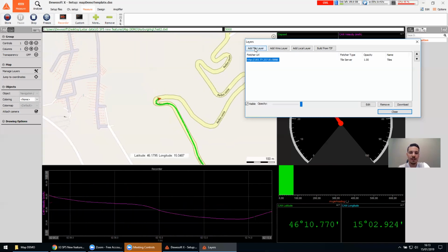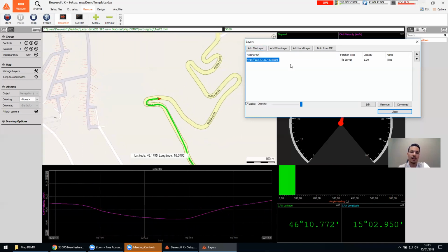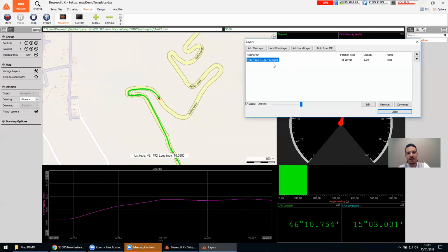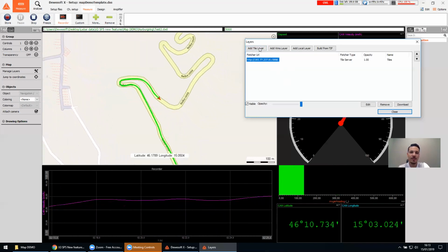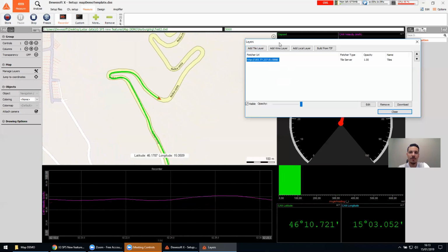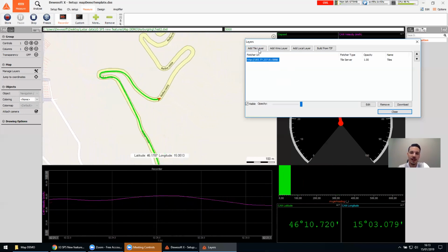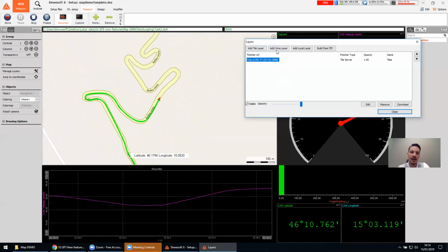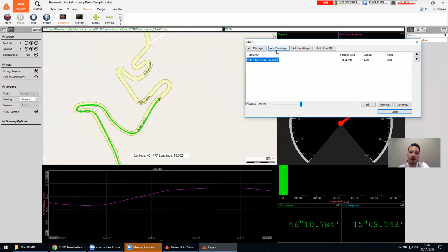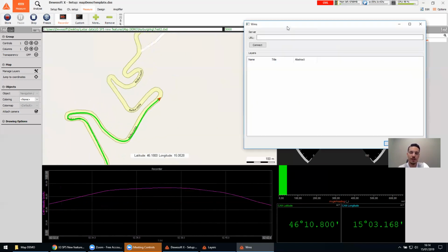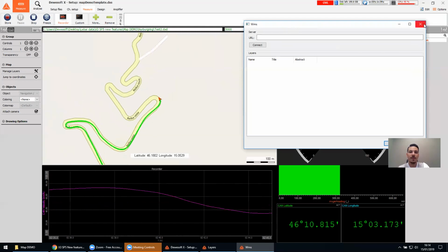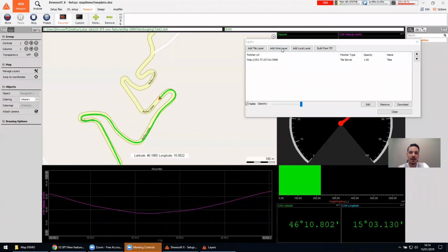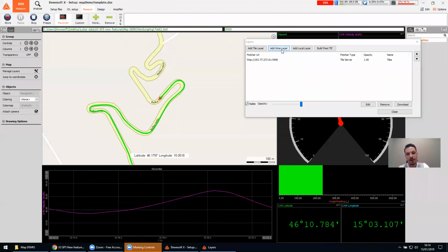As I mentioned, the image that you're seeing right now is a tile layer. In the industry of map imaging, we've got two most standard options. One is tile layers and the other one is WMS layers. At the moment, Dewesoft provides you with a tile layer. We don't offer a WMS layer, but if you or your customer has access to a WMS layer or a WMS server, then you can add it through this interface right here. It will work in basically the same way.